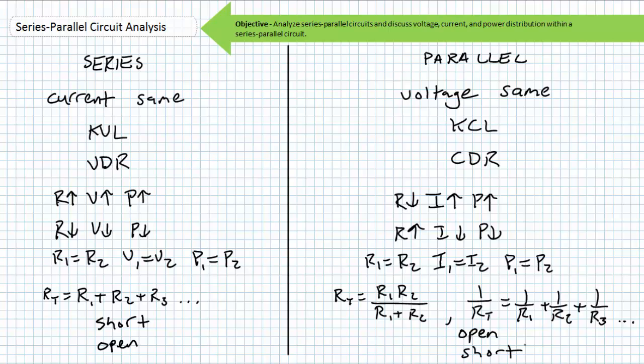These series versus parallel properties are always true, and their application to circuit analysis and troubleshooting must become real, visceral, and instinctual. This cannot be accomplished by watching an online lecture or playing around with circuit simulation software. You must get inside a hardware lab and practice and apply these techniques on real-world components using real-world instrumentation. You will make mistakes and things will not go smoothly at first. But realize elements in series with one another must necessarily carry the same current through them, and elements in parallel with one another must necessarily have the same voltage across them.